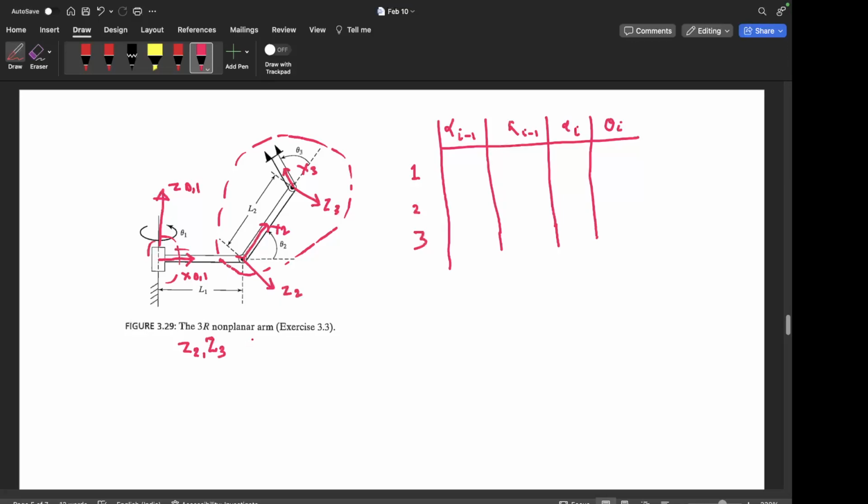When we apply the same thing here, sir, for x3, there is no z4, no sir? So for the extreme last end, there will be only one axis, that is z. I mean, only one frame will be available, no sir? Yes, I get you. Because we have followed a pattern of assigning x1, x0, x2 along the links, that's why we directly mark x3 along the end effector, just by seeing the pattern, no sir? Yeah, right, for the last one.